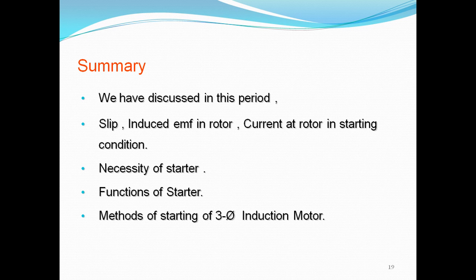In this connection, the star delta starting, we have to take care so that the sequence of the supply connection to the winding terminal has to follow. That is, changing from star to delta, we have to follow the phase sequence. Otherwise, the motor will not run properly.